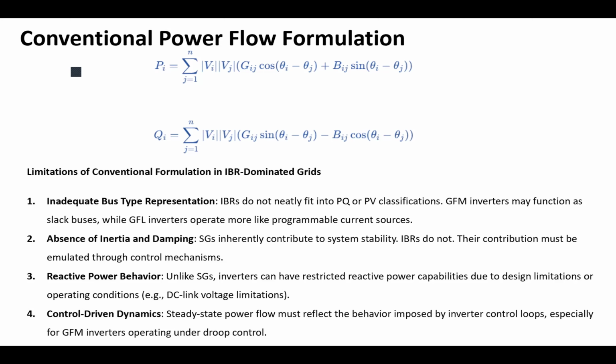For example, if we have a grid following inverter that measures the demand and tries to address whatever is measured at the terminal, based on the PID controller that we talked about. This was the grid following, and they had a PLL for the frequency synchronization.